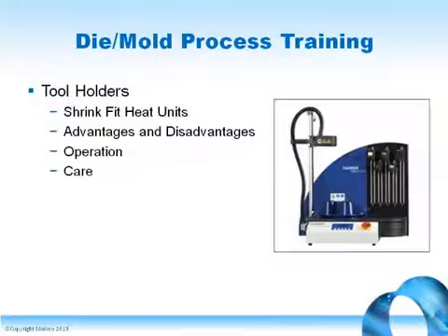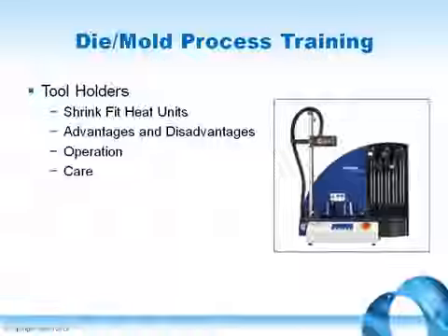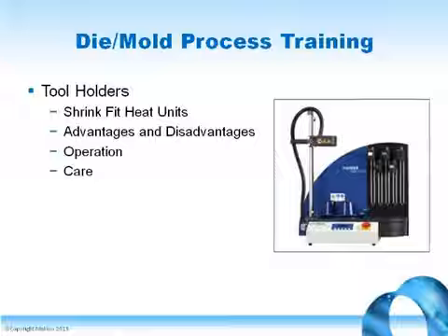Shrink fit heat units, induction type compared to air type. We will look at the advantages and disadvantages of both systems, operation and care. Induction type is faster than air type. Induction type is more expensive. Misuse of induction heat will render the holder unusable. Interchangeable shrink fit adapters, MST, are more cost effective than single piece shrink fit holders. Single piece holders have less runout than a two-piece style. Most shrink fit holders are balanced to Makino standards, yet some allow for even greater balancing.